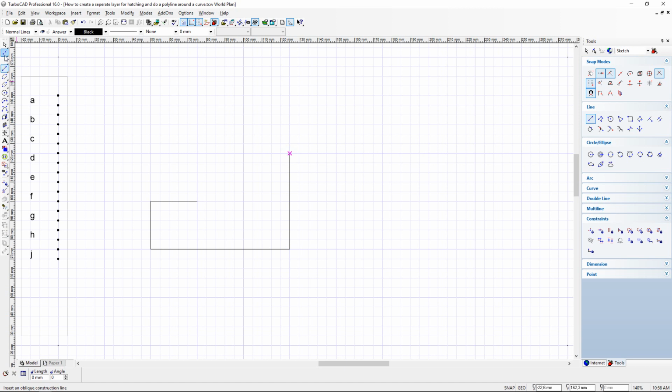Now I'm going to go to the toolbars on the left, where I have an arc, center and radius. I'm going to select that because I just want to draw an arc. I go to this point here and click and drag to the top of that line. The center point is where my mouse is now, and I'm going to use that height as the arc radius. And then I just want to draw, but I went to the wrong side. To fix this, you just right click and cancel, or you could have just pressed escape on your keyboard. So I'm going to do this again.